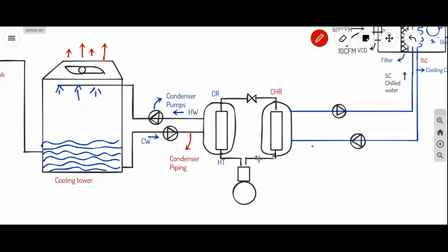Okay, as it is chilled refrigerant compared to chilled water return at 15 or 20 degrees centigrade, you socho, oh, hot water here compared to the refrigerant temperature. So we'll supply hot water. Now here heat exchange hoga, chilled refrigerant will become hot refrigerant and hot water will become chilled water. This chilled water is supplied to the AHU to make the cooling, in the cooling coil.